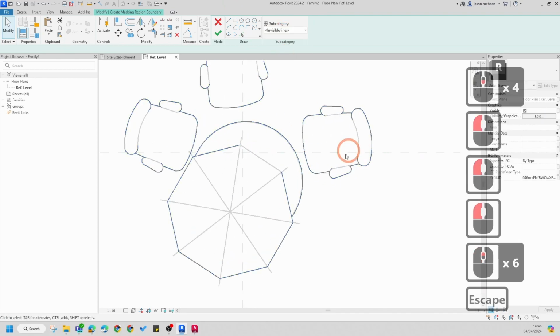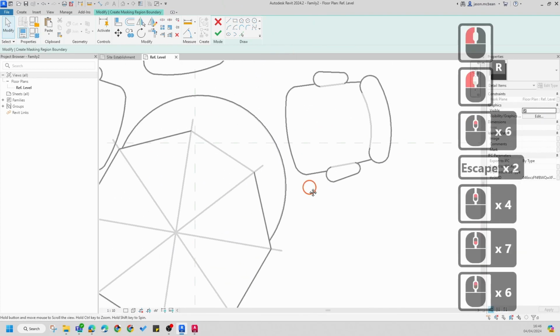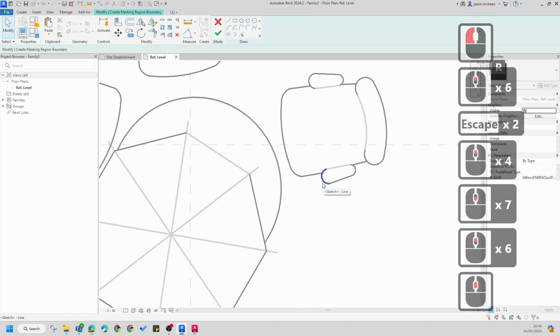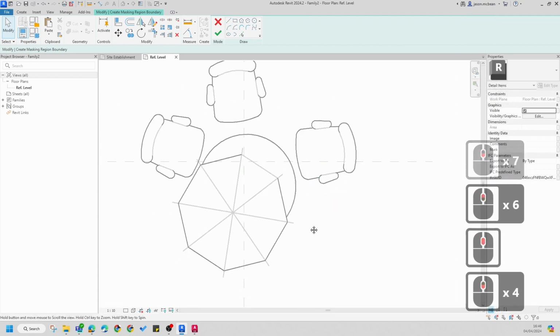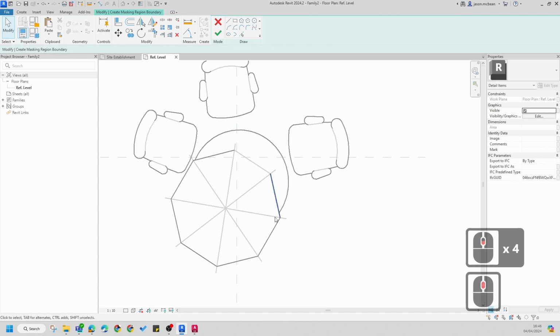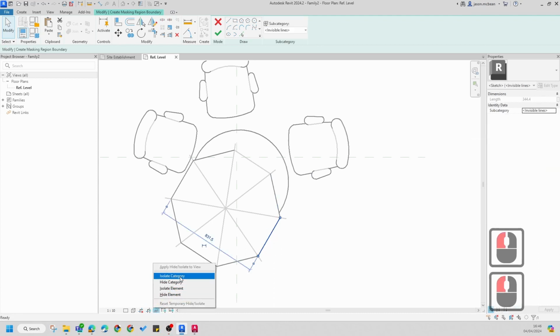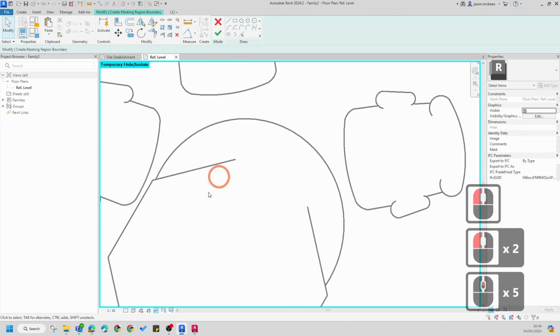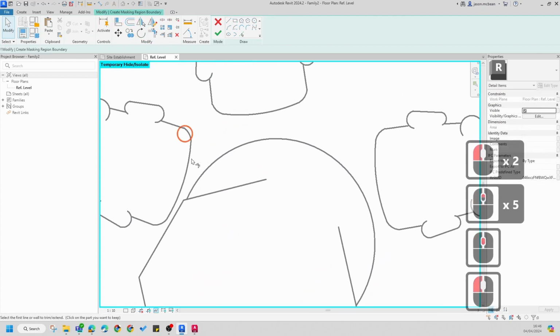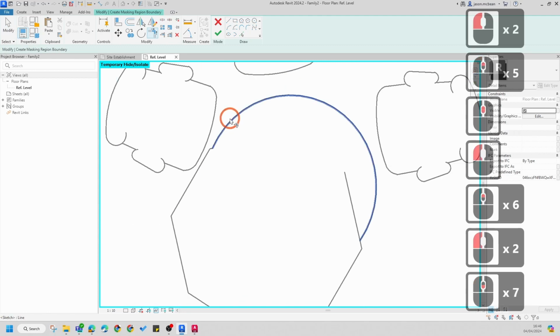These invisible lines have a gray hue to them, just so that you can see them in this view, but they'll disappear once you put them in the model. So now select one bit of the line work, and I'm going to isolate category. So now I can fix this, so use a trim tool, so let's fix this information up quickly.